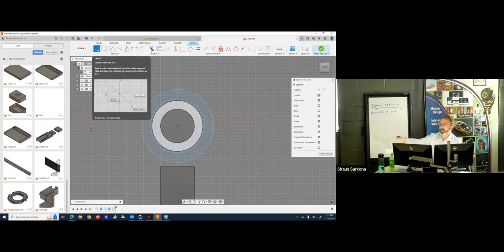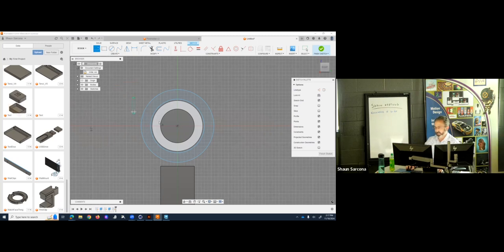This isn't going to be something where it would just slide into it. That's the way it's currently set up. I want something I could just set down inside of it. So I'm just going to draw some cut lines. So here to the middle, and then out to here. And then hit escape. So if I click on this, this is the actual shape that I'm creating. So now I have a spot for my pen to kind of sit inside there if I need it.